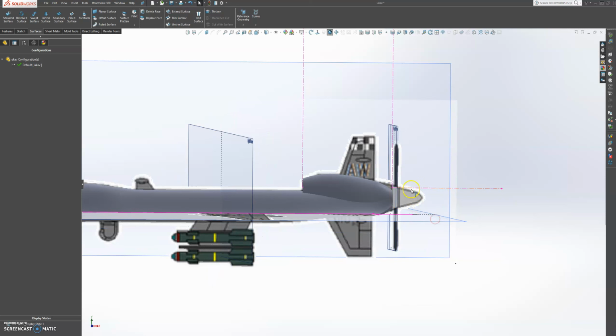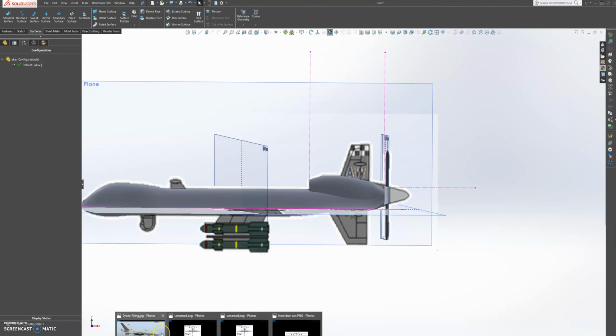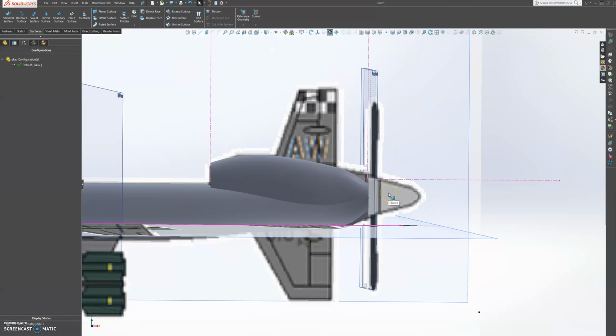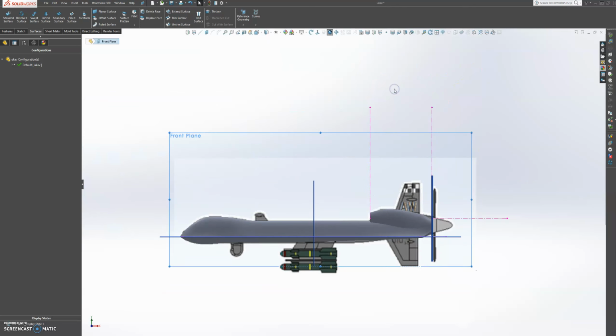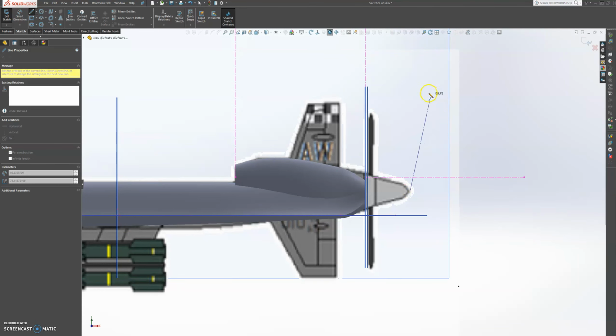So we're going to create this motor mount here. Don't worry about that. We didn't follow our drawing, because we are not following our drawing. We're following mostly this drawing here. So let's look how far that goes out. Let's make a reference line on that. So let's sketch on the front plane. Let's grab a center line, and the motor mount comes out about here.